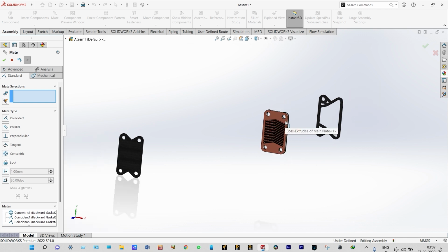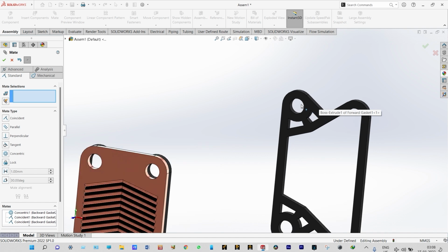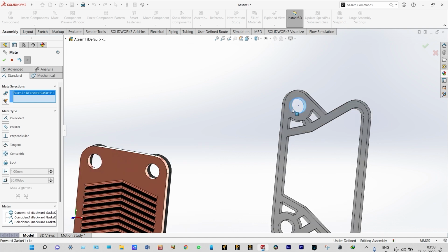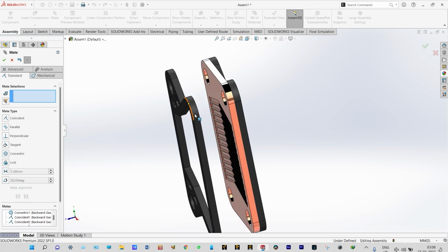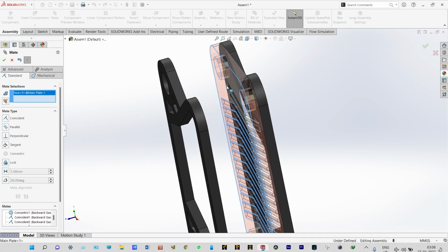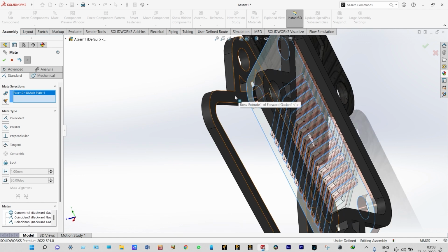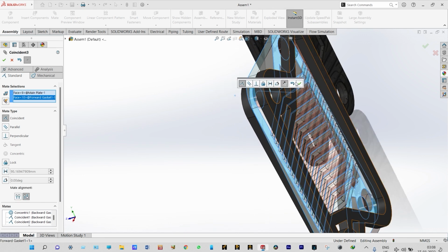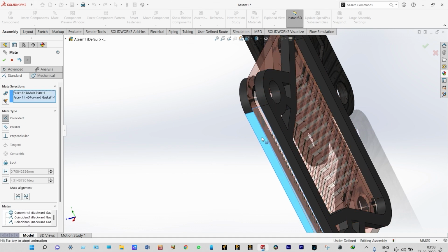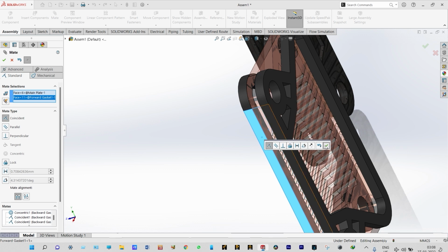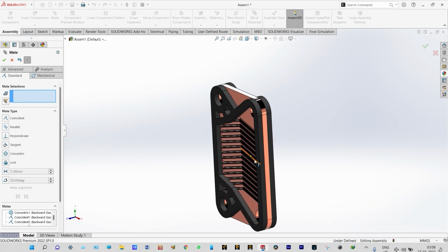In this case we need to provide one front gasket at the front of this one. This is the front gasket that we provided here. So again we can start assembly. That means this hole should be meeting with this hole. One constraint is met, right? Again this side should be meeting with this side. Done. Two constraints are met. Now the sides, this side should be meeting with this side. It should be parallel. Green check, all the constraints are met. So this part is done completely, right?